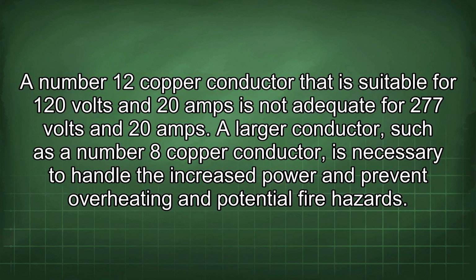A number 12 copper conductor that is suitable for 120 volts and 20 amps is not adequate for 277 volts and 20 amps. A larger conductor, such as a number 8 copper conductor, is necessary to handle the increased power and prevent overheating and potential fire hazards.